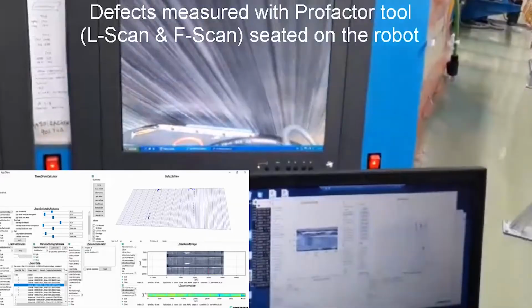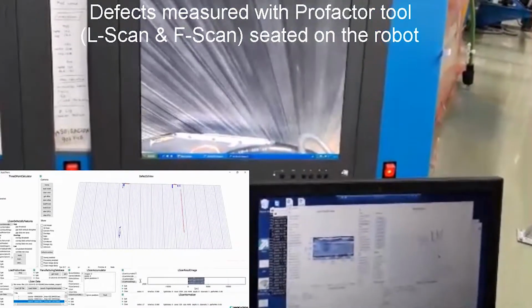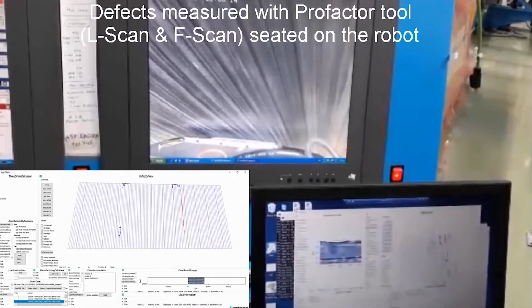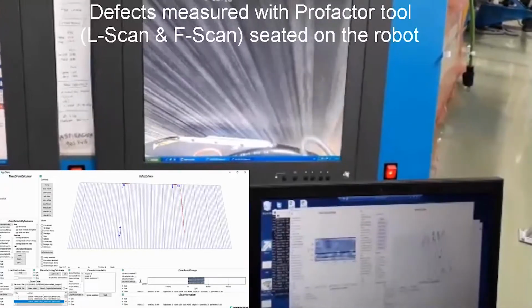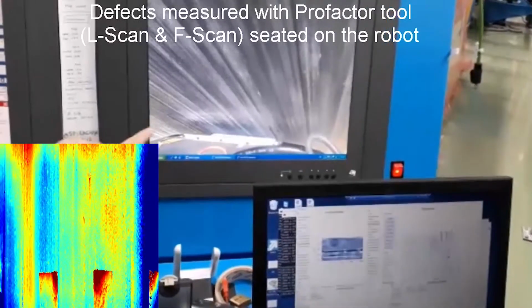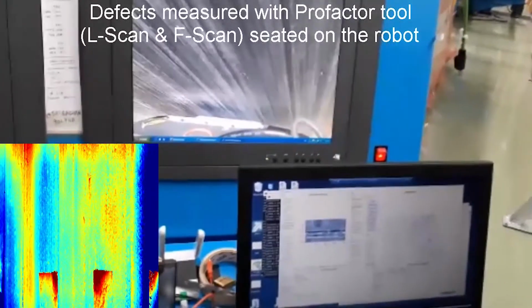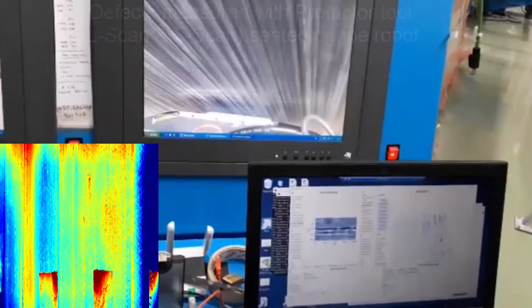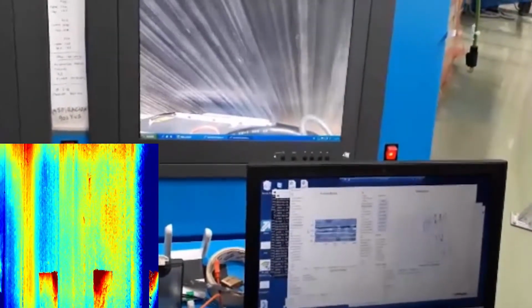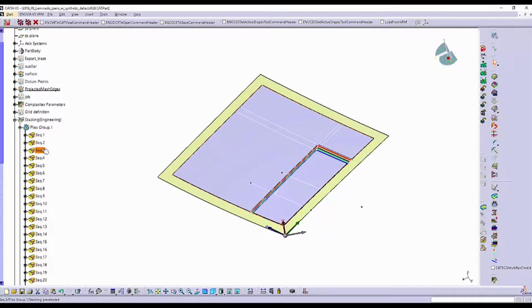For DS, this can trigger the processing of defect data to determine the effects of defects on the structural performance of the component. A significant effort has been made to formulate methods to determine the effects of defects on the structural properties of the component. This is a complex problem, as the effects can depend on the location and the existing loads on the component. It may be that a defect is in an insignificant location, or maybe it's somewhere critical.